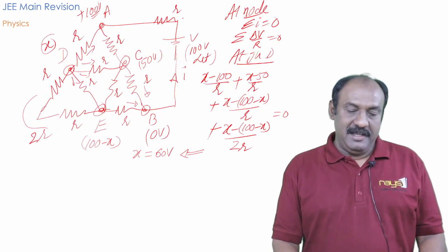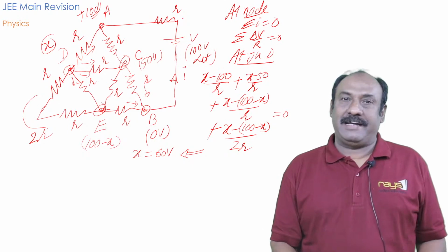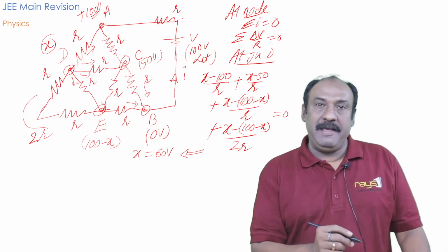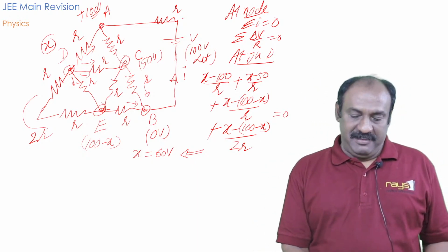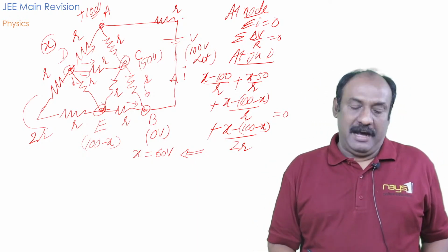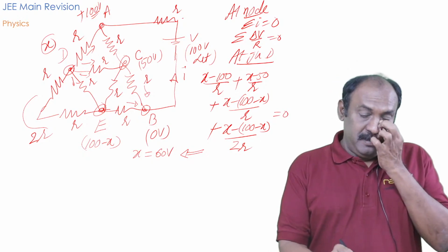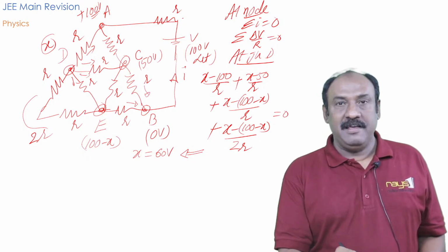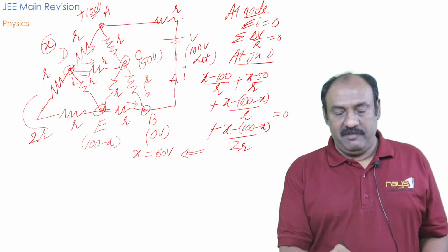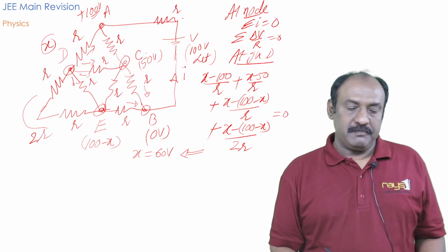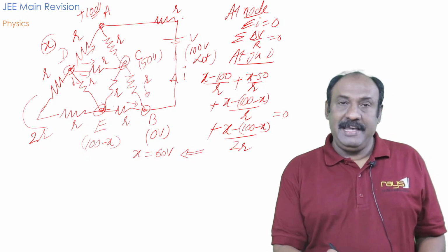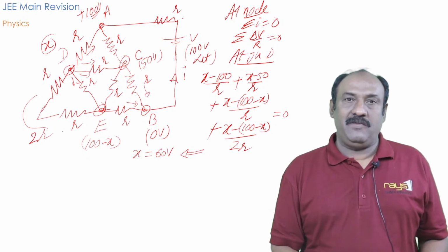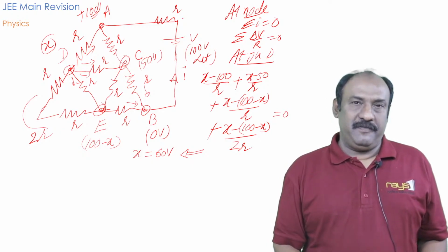What I did here, I considered the circuit and connected a battery of known potential, 100 volt, between A and B. I considered potential at B as 0 volt and potential at A as 100 volt. Along the path ACB there are two resistors, with C at the middle. Out of the 100 volt drop, there will be a 50 volt drop at C. Along the path ADE there are R and R3 resistors, so I don't know in what way that potential difference will be shared.